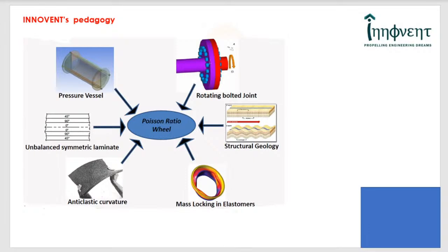Surge is a phenomenon, in the simplest possible terms, where the ability of the compressor to push the air is lost, and as a consequence, instantaneously with a big bang, the flow is discontinued, and the flow also gets reversed, and the combustion can move both forwards and rearwards, a very damaging phenomenon. So a single component, if not designed properly, can affect several of the performance parameters.